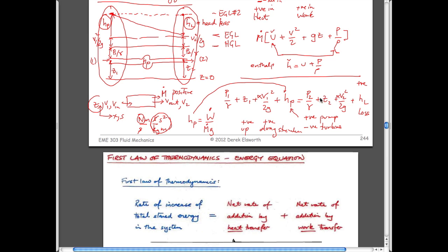And so the assumption is, if you have flow going along a stream tube, that the velocity it comes out at is uniform all the way across it. And if that's the case, alpha is equal to 1. If in reality it comes out so that it looks something different to that, then alpha is less than 1. So it's just a scaling factor for the fact that flow is not uniform across the stream tube.